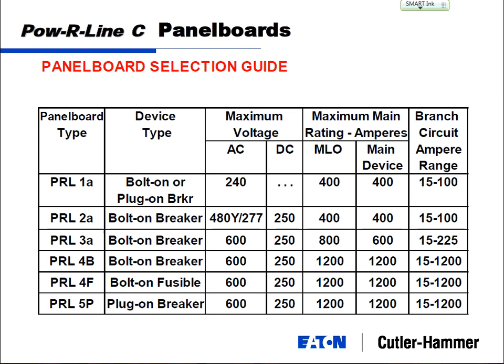So inside the circuit breakers, we've got two functions. We've got a thermal function, which is basically two pieces of metal inside the circuit breaker; bimetallic might be the way you'd hear it. Different kinds of metal: as the circuit heats up, at 20 amps you're fine, at 25 amps this metal is going to gradually bend, and if you're over the rating of that metal, it's going to bend to the point where it hits the trip bar and trips the circuit breaker.